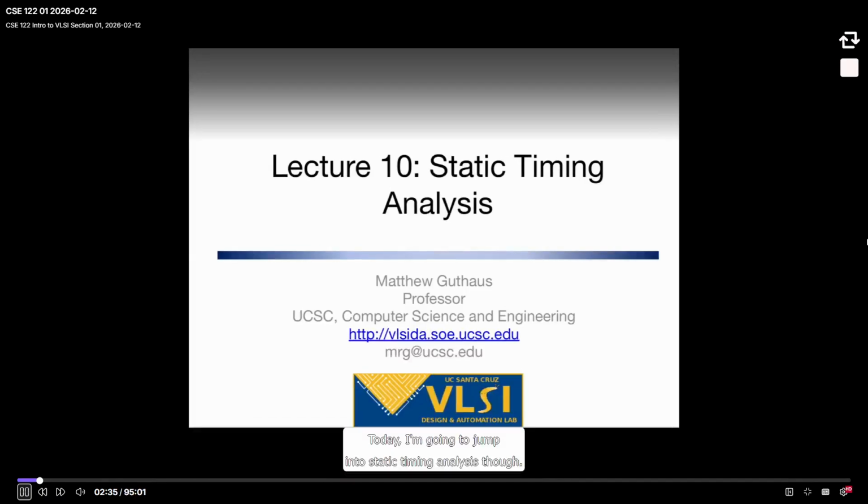Today, I'm going to jump into static timing analysis, though. So static timing analysis, everyone has done FPGA design, right, in 125. It's also used for ASIC design, and it is probably the most undervalued part of chip design because it impacts your RTL development, impacts your placement and routing, impacts your final sign-off. Basically, this crops up everywhere in design. And there are entire jobs at companies that are static timing engineer. I know one of my master students just interviewed at Apple for that position. So it's a very important area with lots of work needed on it.